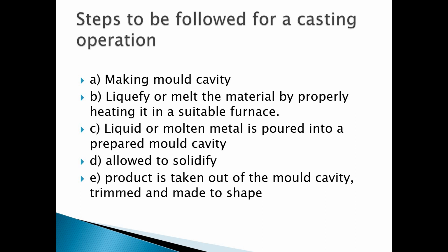For melting purposes a lot of types of furnaces can be used. There can be an electric arc furnace, a cupola furnace, an induction furnace. A lot of types of furnaces are available in industry. As per availability in our foundry, we can use that method for melting, and then we prepare the liquid metal. So the second step, preparing the liquid metal, is important.